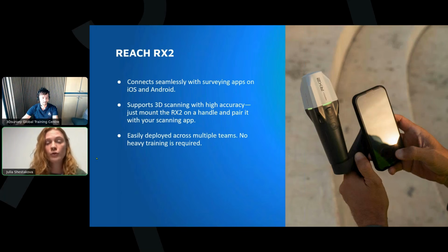And then on your phone, an Android phone here in this integration, you can use the mock location feature, which substitutes the position of the phone with the position it gets from the receiver. So later on, you can easily use the position of the receiver right in the phone. And you can see that this offset of the receiver relative to the phone is fixed. So it's always the same value, and it's also considered. And with photogrammetry, or videogrammetry, to be more correct, you can get this point cloud, and get this data collected and processed together with the receiver. You can accurately georeference it in space, so know where exactly it is located, again, with centimeter accuracy.